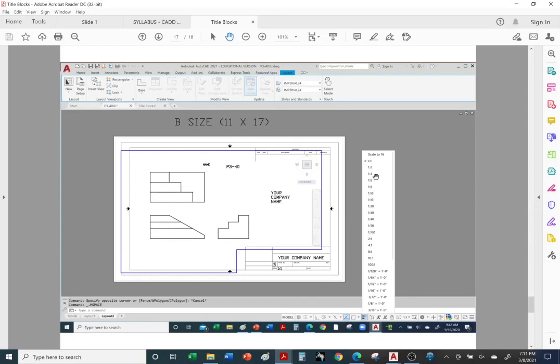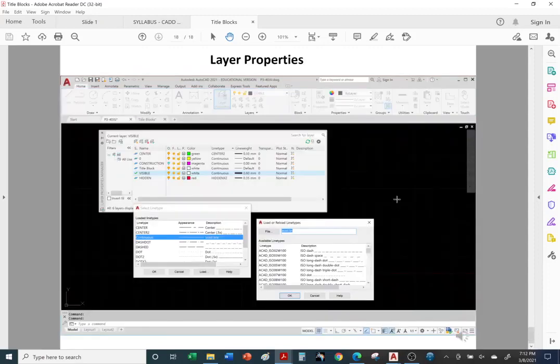Sometimes I will deviate. Like I shouldn't be using 1:3, but sometimes 1:2, which is half scale, or quarter scale, 1:4, that doesn't quite do it. Then I'll use a 1:3, but I try and avoid using those odd numbers like 1:3, 1:7. Those are not good standards to follow, or numbers to follow. If you're using the standards, you want to use what's standardized.